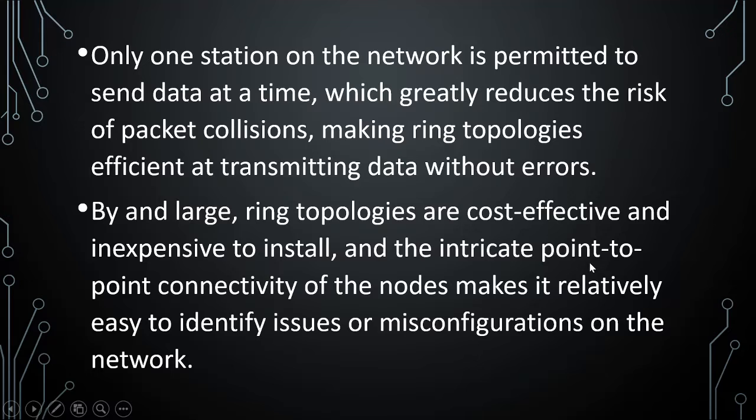For example, what is called a point-to-point antenna. It is wireless, but your transmitter antenna or transceiver antenna must be focused on your other transceiver. If your antenna serves as the receiver, the beam of your antenna radiation must be focused on your transmitter, because if it is lost, it will not be able to receive data.